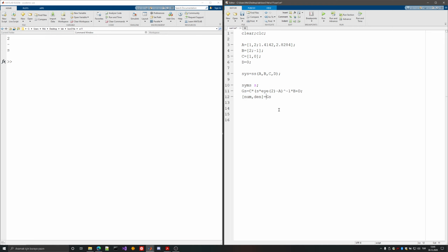Since I need the step responses of both, I need to convert this into numerator and denominator, and then the num will be the double of coefficients of this num vector, and I need all the coefficients of s in order to be able to define the numerator and denominator and pass them to the transfer function. Now I should maybe update this so I have this, and then we will just use the tf.